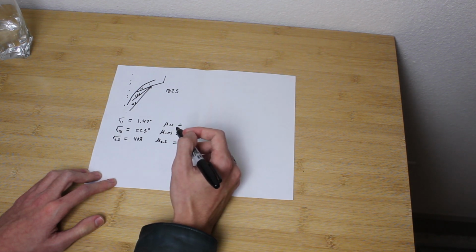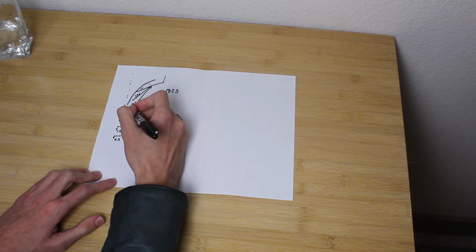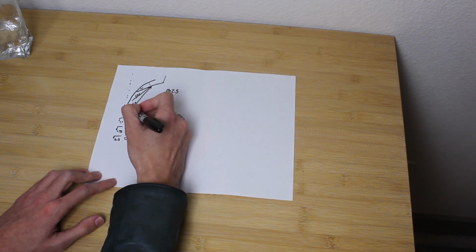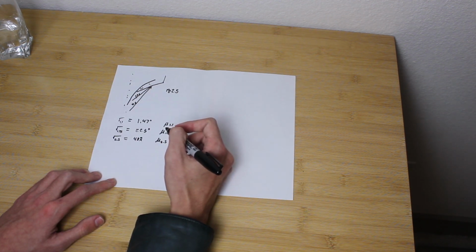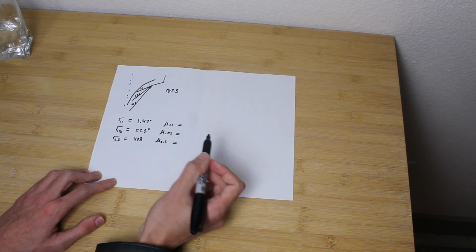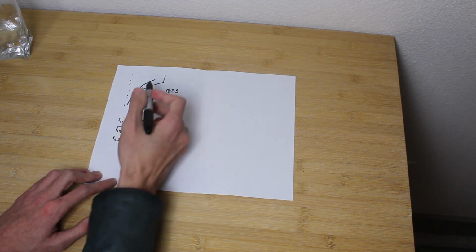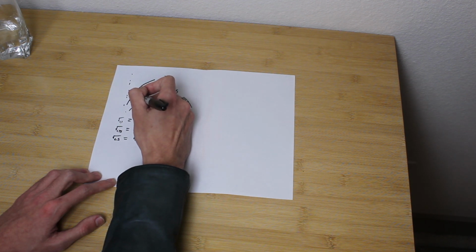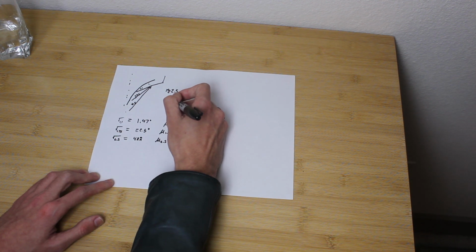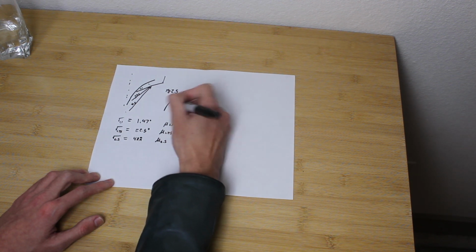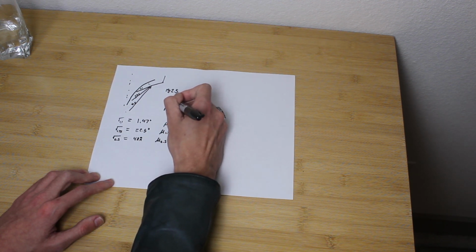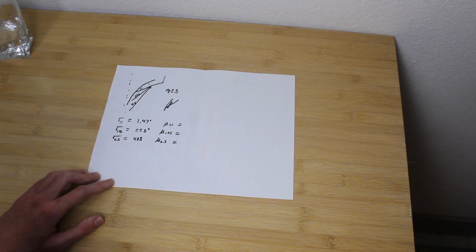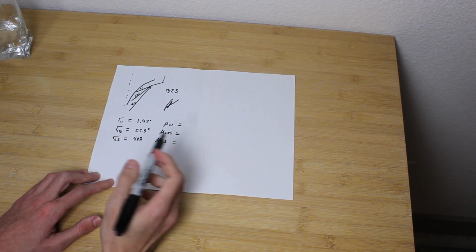Mach angle is the angle between the flow velocity and the local Mach line when the flow is expanded to the Mach number for that particular Mach line. So if we're looking at the case of 1.75, the flow will be moving along the spike, and the question is, what is the angle? If you've got the spike here and a Mach line coming in like this, and the flow angle is like this, what is that angle there? Just to zoom in on that.